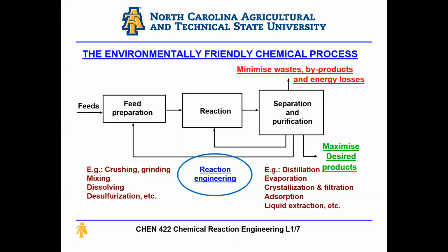And then after the reactor, you usually have another step of physical treatment. However, in this case, this is more of a thermodynamic treatment where you have either distillation, evaporation, filtration, absorption, whatever it is, to try and enhance the purity, remove any junk you have, try to recycle some of the feed, all of this stuff, and also minimize waste, minimize energy losses, all of this stuff. So the first and last steps, you usually deal with them in your separations class, in your heat transfer class, as well as in process design.